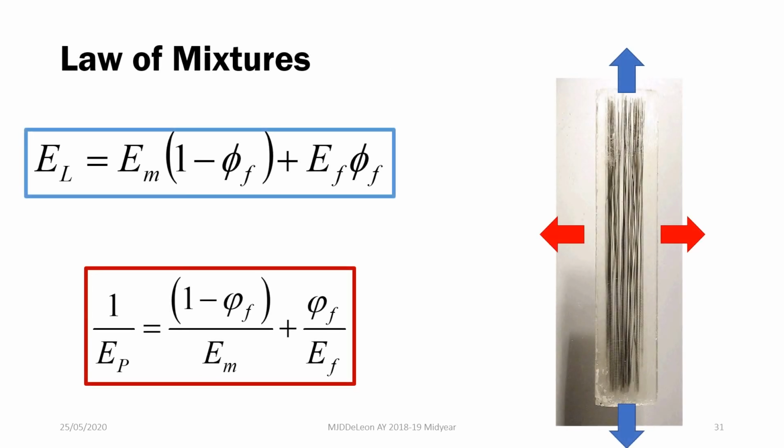So for fiber reinforced composites, we also have the following law of mixtures. So the law of mixtures here covers the longitudinal and the transverse property. So for your fibers, usually mas maganda yung longitudinal property niya. The longitudinal property is the property aligned with the fiber axis, compared to the transverse property. And their resulting properties depending on the axis of loading is given by the following equations on the screen. So for now, hindi pa naman natin kailangan yung mga equations na yan.